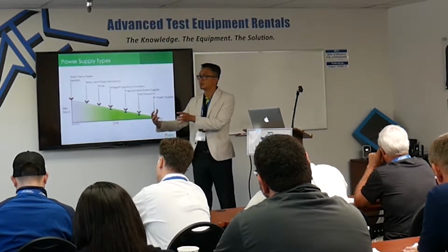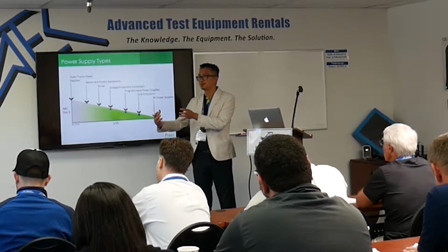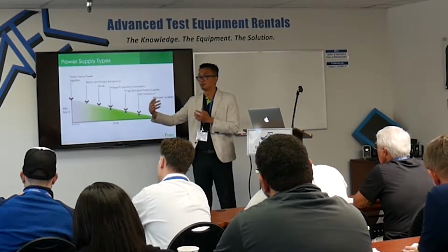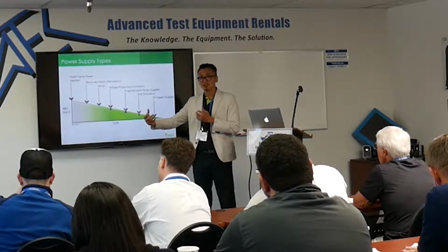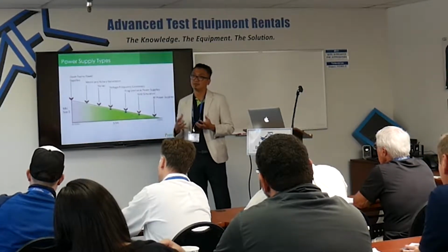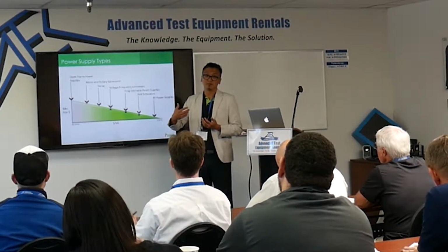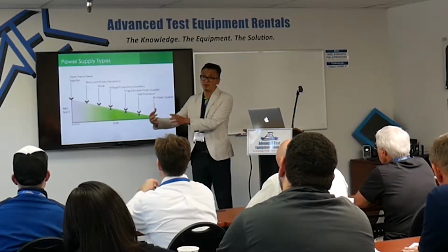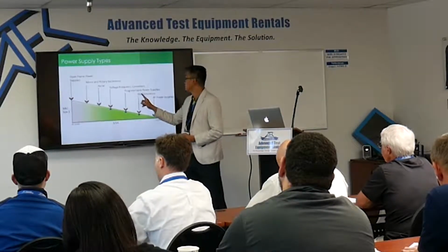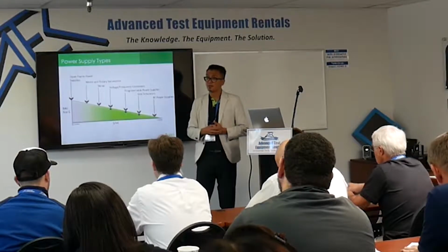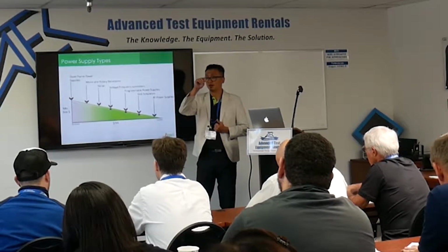You want to simulate the grid because the grid system will absorb the power from solar systems and wind systems. So you have to simulate the voltage and frequency and observe the power on your PV inverter as well. So usually a grid simulator sometimes needs to be bi-directional,